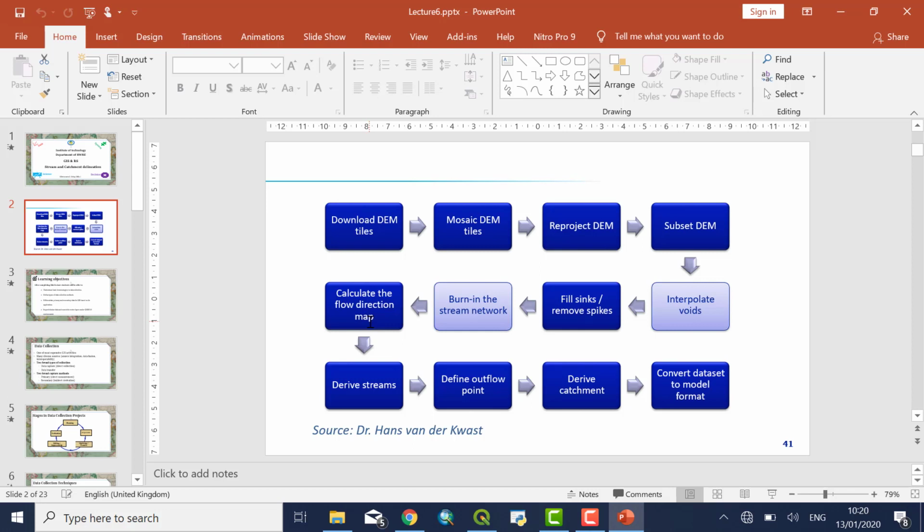These 8 discrete directions are 0, 45, 90, 135, 180, 225, 270, and 315 degrees to the steepest cells downwards, while the D infinity algorithm uses continuous directions. In our case, we are going to use the D8 algorithm, which uses 8 discrete directions or degrees.